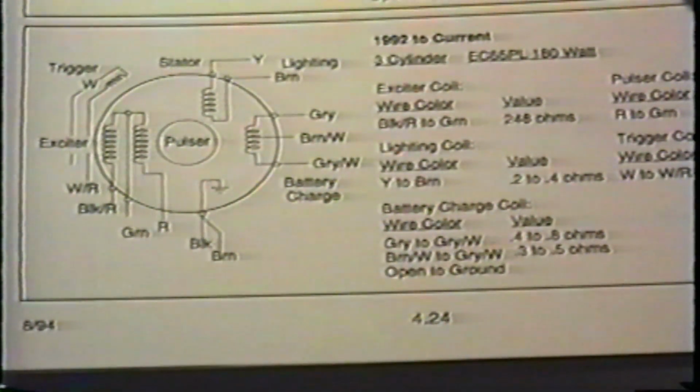To identify the type of trigger system used, refer to the schematic diagram in the Master Repair Manual. Some diagrams may refer to the trigger coil as a pulse or control coil. The name may be different, but their function is the same.